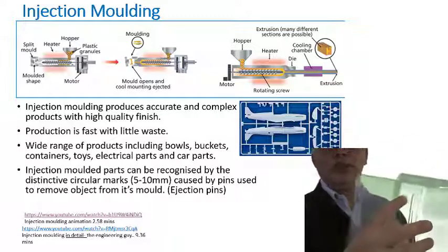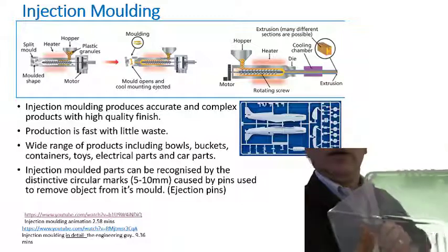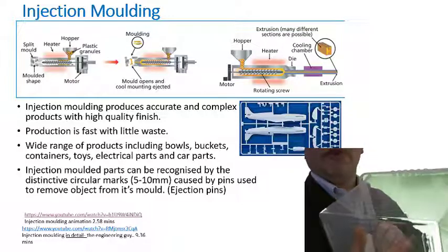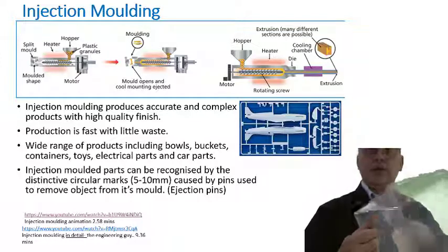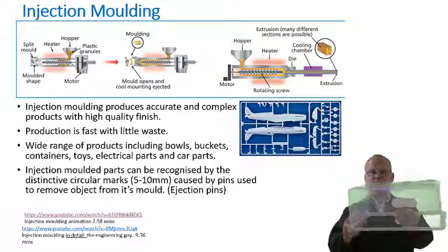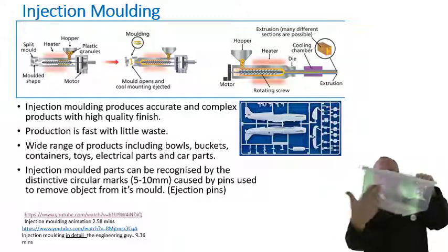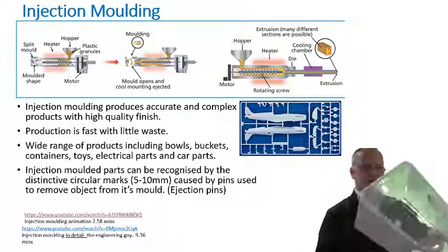And I've also got, you can't see this in the video, but there's a little tiny triangle. There's a little triangle there, and that triangle shows it's got number 5 in the middle and it's got PP. That shows me that this material can be recycled and it's polypropylene. So an injection molded tool has created that very precise, very repeatable, really good quality product because it's got a polished material in there. So that's a great example of injection molding.